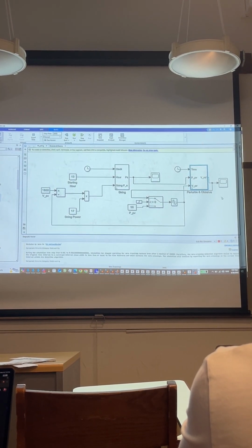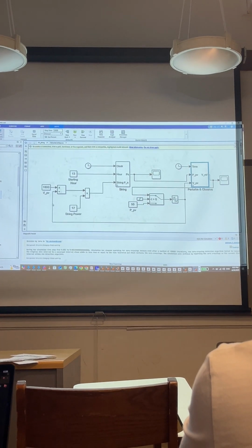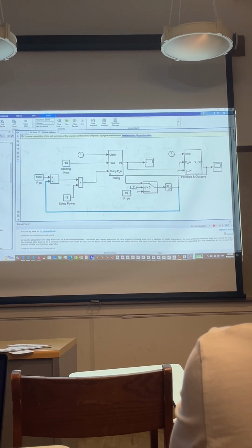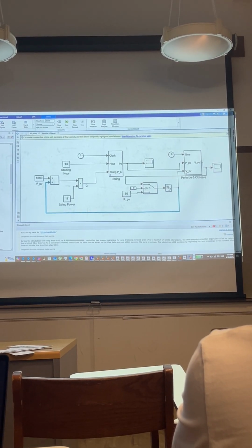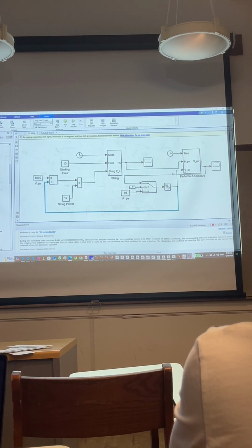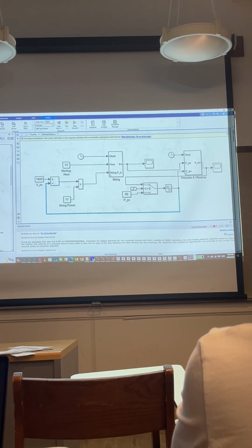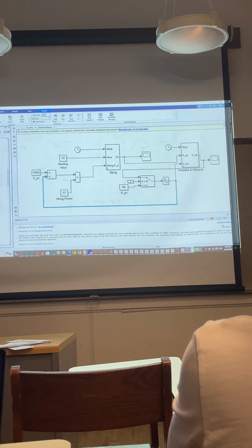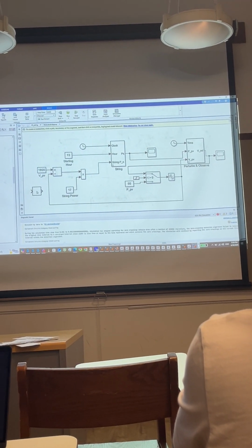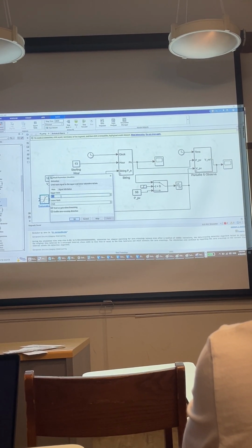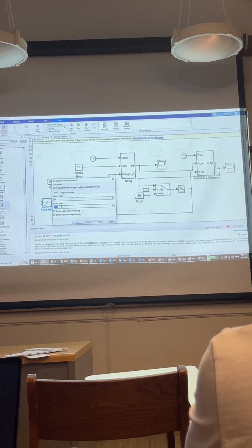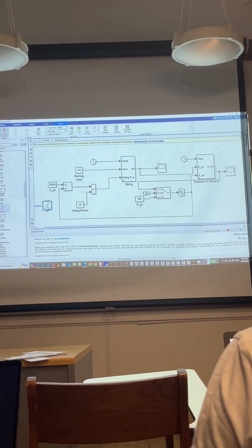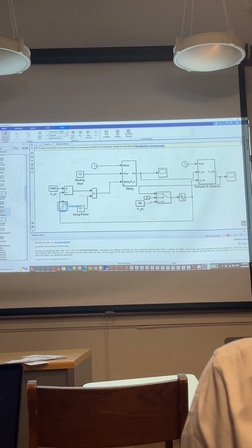So when I'm adjusting the voltage here, maybe I could use something like a saturation here to not go to negative values to make our lives easier. So with that, it's going to be adjusted. So let's do a discontinuity here with the saturation. The saturation should be upper limit infinite, lower limit, let's put it 2.